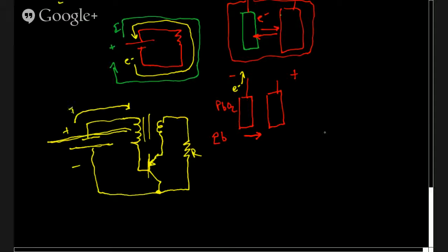Why did you stop working? There you go. If you think of it as current reference direction, when this circuit first gets turned on, when you first connect the battery, there'll be a positive voltage. We'll saturate this inductor, but an inductor allows DC current to pass, and it'll turn on this transistor.